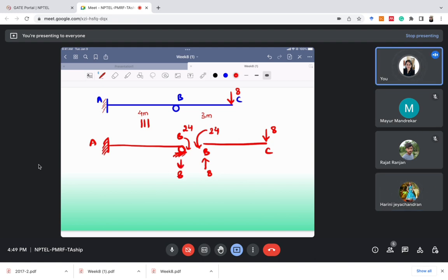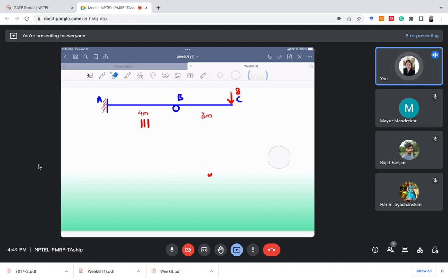Okay, so if you do not want to make the free body diagram, whenever there is an overhang part, just remove that part, ignore it, and instead make whatever moment is coming from it. So here it is 8 kilonewton point load at 3 meter distance, so moment will be 8 into 3, simply 24. Just make it as 24 here. Is it clear?